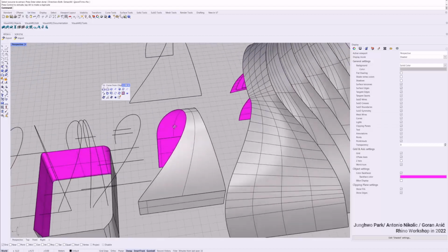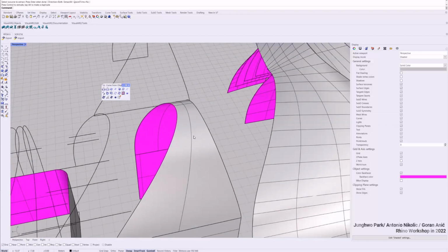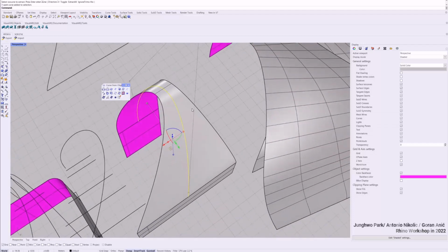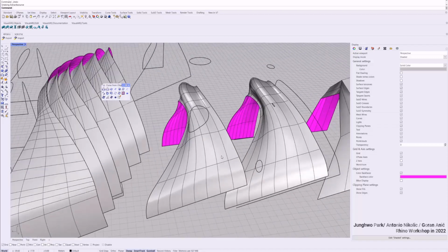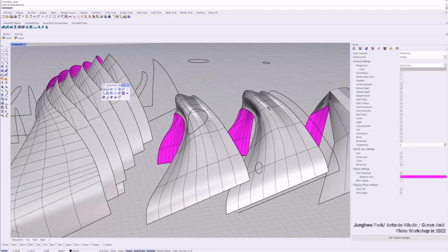Okay, that's very nice. Why is it important? If I repeat and instead of both I choose the V direction, maybe I'll turn on the midpoint here. Then you get the V direction of the surface UV, and you can maybe split it, then you get two surfaces. There is a direct tool to split without extracting the curve, which I'm going to show you later. But anyway, extracting curves is useful when you have to keep modifying your surface.